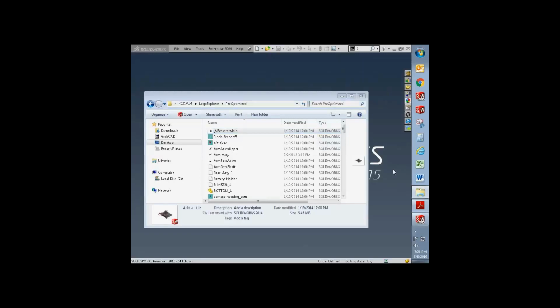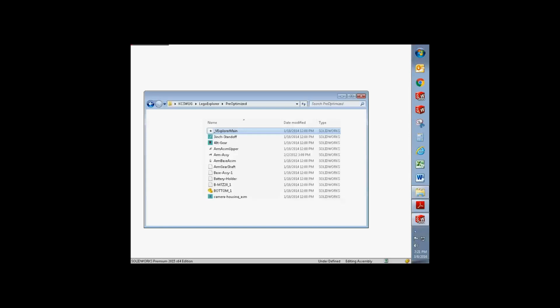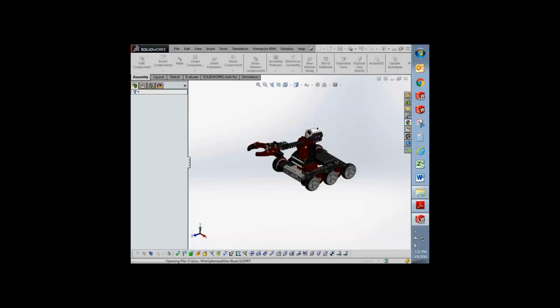So for the fasteners, there is one limitation I'll mention up front. SolidWorks does have an option to lock rotation. If you click on the mates, I think it might be a 2015 feature or might be a 2016. But you can just select the mates in the SolidWorks tree and say lock rotations, and it'll lock it for all the concentric mates. It's very useful for the fasteners. Motion does not use it yet. But that's something you can do at the SolidWorks level to make it a little more efficient for solving.